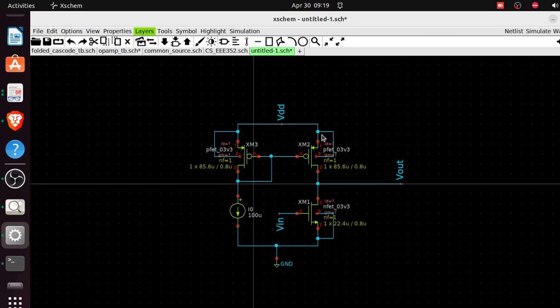Putting this current source here makes it part of the design, but since it's not something we can fabricate directly, we make the amplifier less dependent on it, so we can just use an external biasing for the amplifier. So this is really not part of the amplifier.